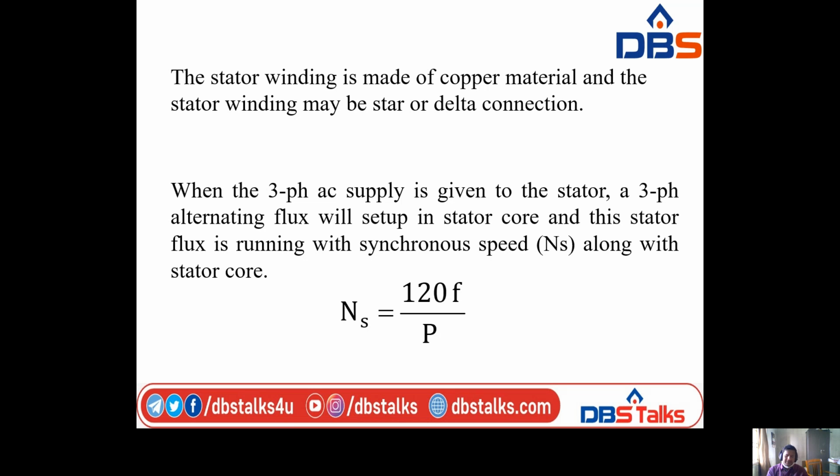slide, a three-phase alternating flux is produced that may be rotating with a synchronous speed. That three-phase alternating flux is also called the rotating magnetic field, RMF, that may be rotating with synchronous speed along the stator core. So look at the picture clearly. That rotating magnetic field is rotating with synchronous speed, with the empirical formula Ns equal to 120 f by P RPM.